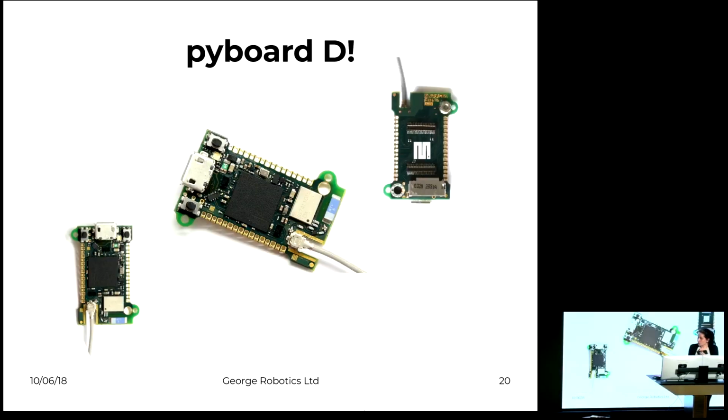So yeah, the new PyBoard D, it's called. It has more functionality than our PyBoard 1.1. It's only 2.4 grams. It's more power, so it's with a better efficiency. It runs on M7 with 260 megahertz and 256K RAM. So it's really low power consumption, and it's a ready-to-use module, but still in the size of these ESP32 models you might know. So there's a Wi-Fi and a Bluetooth chip enabled, which are already ready to use.